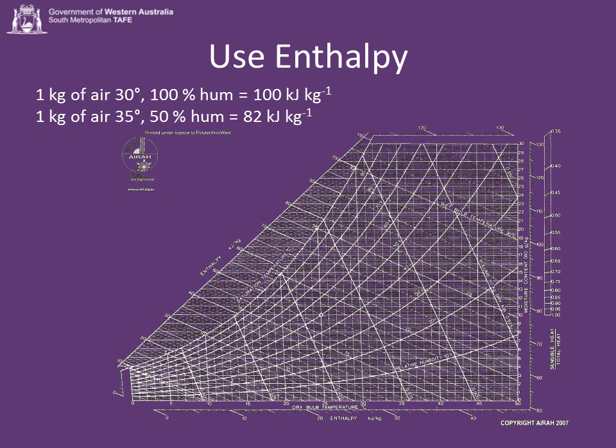That's particularly important when you consider that return air is nearly always very, very high humidity because we breathe out moisture. In Perth, our humidity is normally around 40-50%. So if you have return air coming back at 100% and outside air coming in at 50%, it's nearly always better to use the outside air. And we're not doing that.